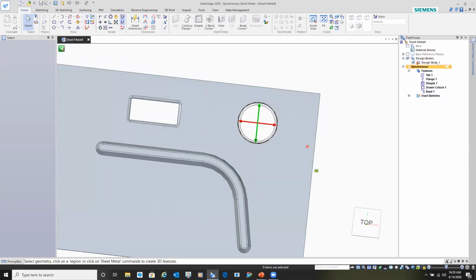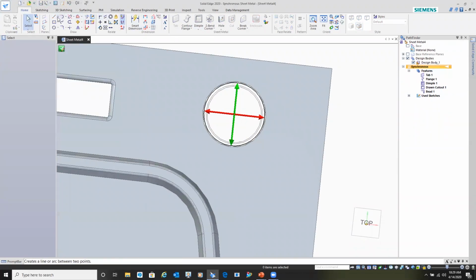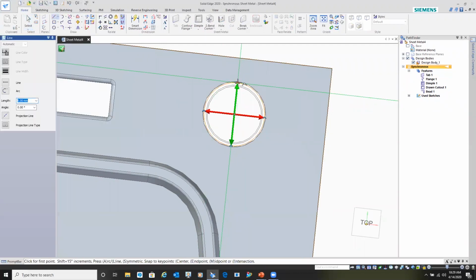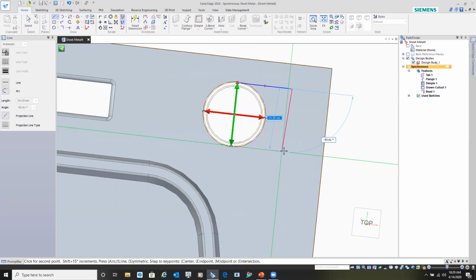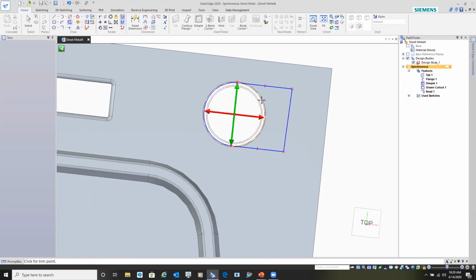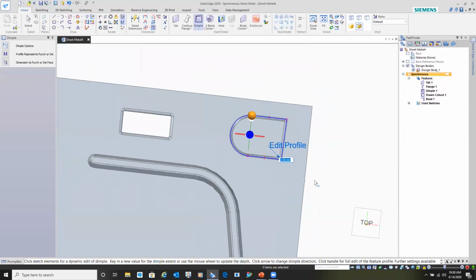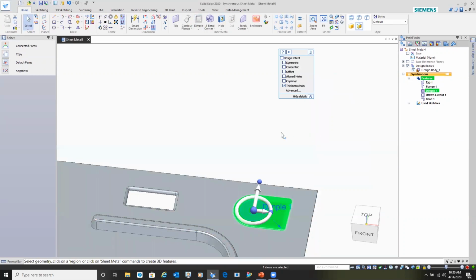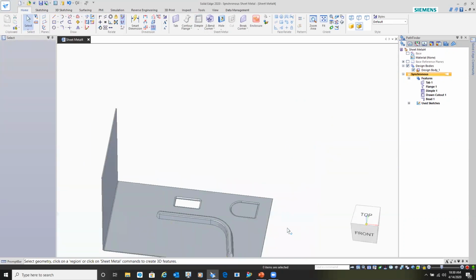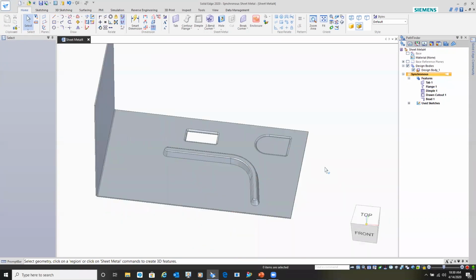So I can actually go in now and I can modify this sketch by picking up, let's say draw, and what I'm going to do is pick up on that point, come across, line it up, and then come here, and then we'll use our trim command. And as long as I maintain that closed profile, it'll go ahead and change the dimple for me. And so even though it was created with a sketch with our deformation features, it will embed it into the features so you can make edits like that.